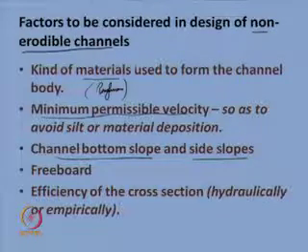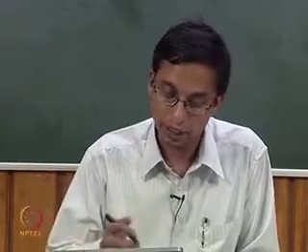The next important criterion is the freeboard. What do you mean by freeboard? Okay, we will discuss it in an expanded way. The amount of height, the free height, which you are going to give beyond the normal depth of the flow for the given design, is called freeboard. We will discuss that definitely.